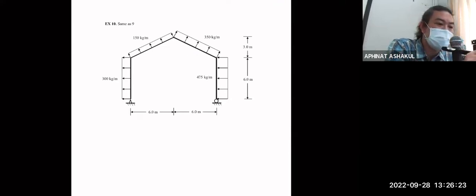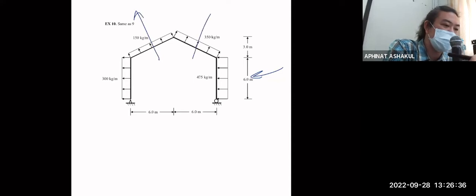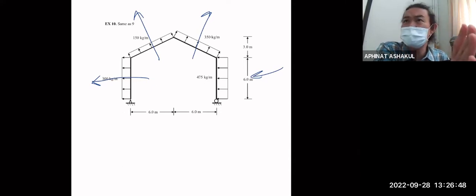Because when the wind blows in here, what happens is that it's just going to hit the building on one side, but then it's going to create what we call suction. It can suck up the building like that from the wind pressure. So this load is true. I just want you to have one condition that, okay, that's why we do structural analysis, because it actually happens.